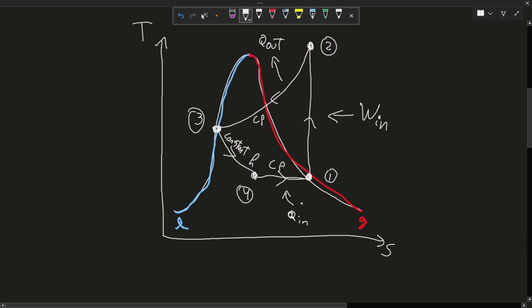If you're allowed to have a crib sheet, you should copy down exactly this TS diagram, okay? So, for this chapter, they're going to ask you some questions. They're going to ask you for the COP. This is the coefficient of performance, which is just a fancy way of saying how efficient the refrigeration is. The COP is going to be equal to the heat that comes in divided by the work being done on your system.